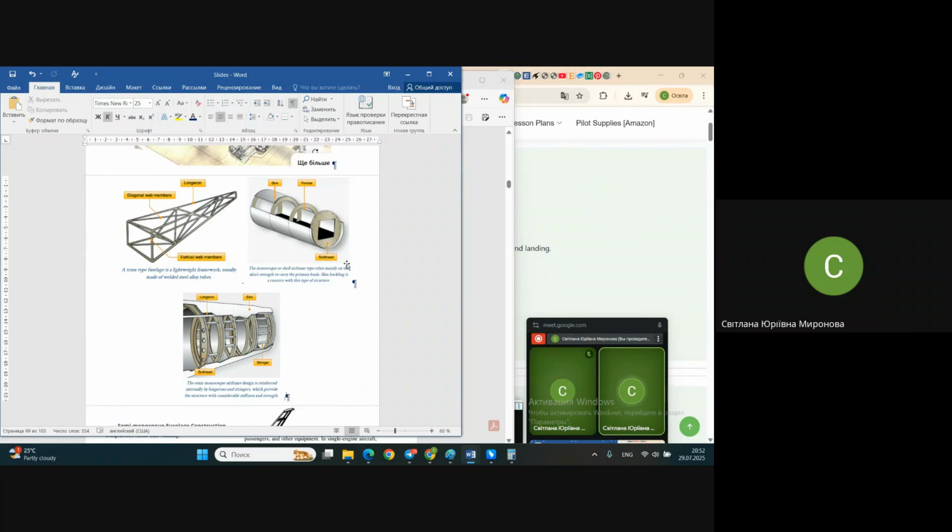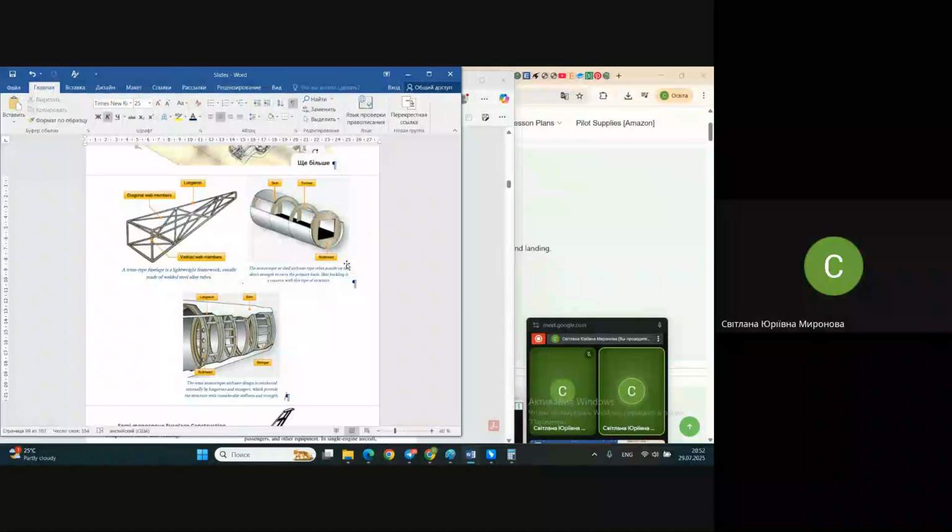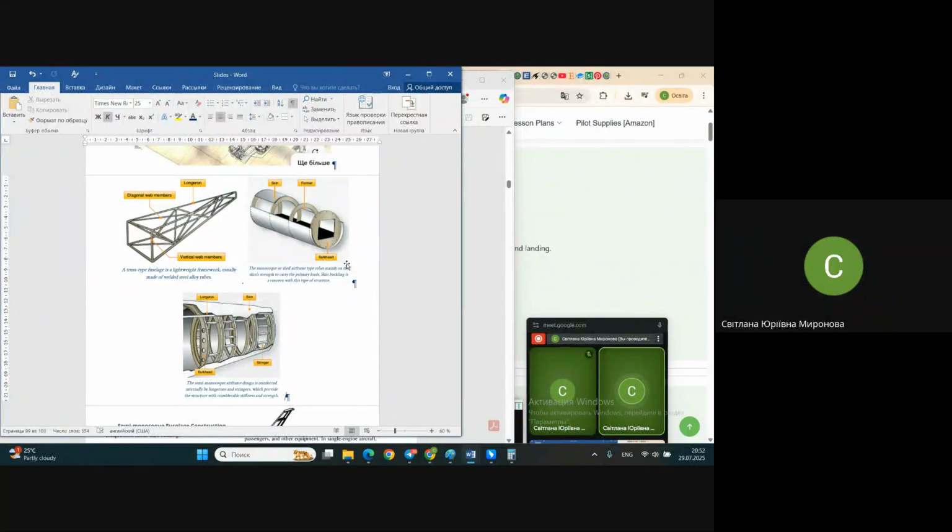These longitudinal and transversal elements are covered with skin, and altogether this grid of elements in longitudinal and transversal direction, covered with the skin, works all together like one beam. And these structures in the fuselage have names, a nomenclature: frames typically, and stringers for semi-monocoque structures,